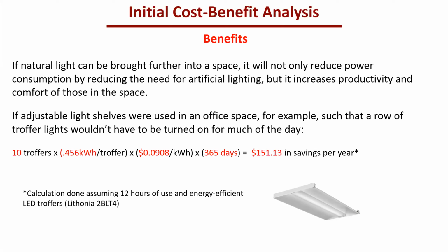The other thing is that you can have energy savings, of course. So the example I used was if we had a row of these shelves installed along the side of an office area, and it was reflecting enough light that we didn't have to have a row of 10 troffers on, these 2x4 lights you typically see in grid ceilings, that would be $151 per year, and that would just compound every year.